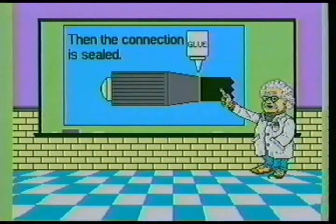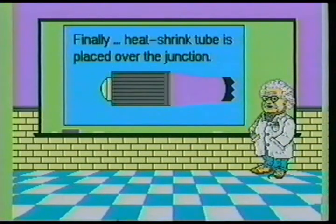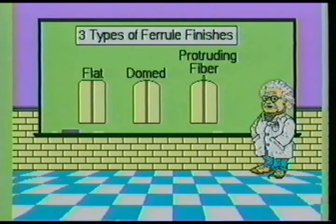Next, the metal part of the connector body is crimped or glued to the protective coating around the fiber core. Finally, heat shrink tube is used to seal the cable connector junction. This reduces the chance of contaminants entering the connector. The three most common types of ferrule finishes are flat, domed, and protruding fiber.